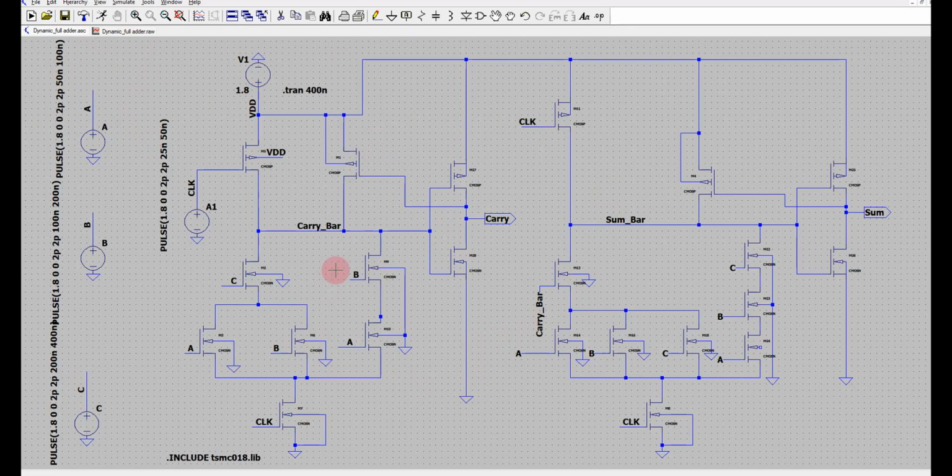And also, as a home assignment, you can try out making flip-flops. Okay, a D latch I had discussed in the last class, and I have shown you a small demo of how to design a D flip-flop. So you can read your textbooks, or you can Google using master slave flip-flops. You can make master slave latches. By using 2 latches as a master and a slave, you can make a D flip-flop. Okay, only thing is a complementary clock is to be given here.